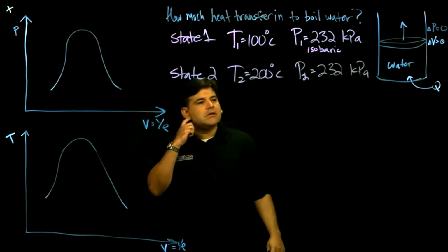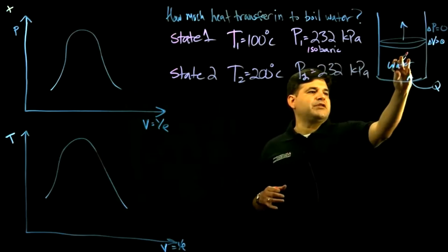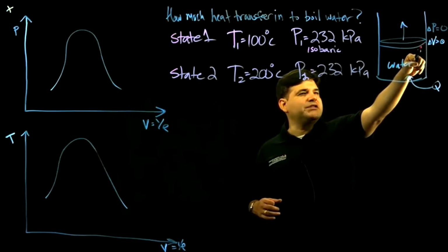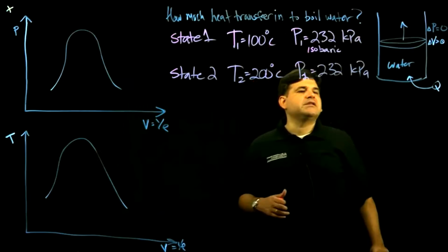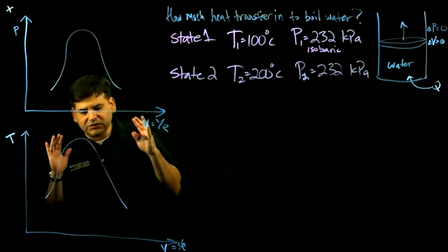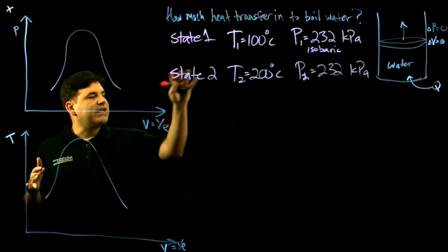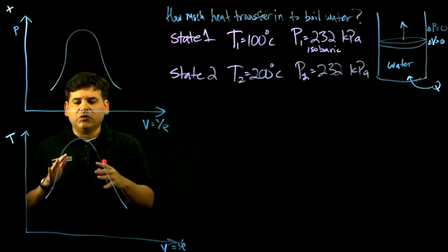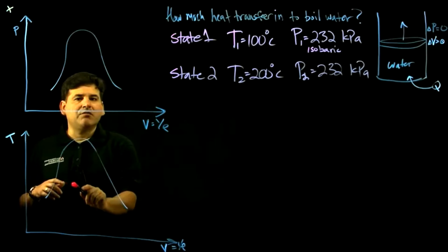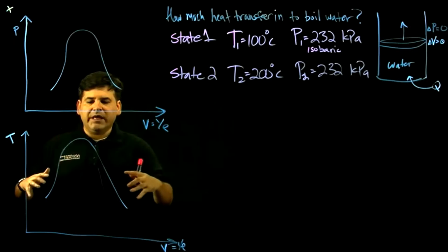All right. So we're going to analyze this going from an initial temperature, this heat transfer comes in to keep the pressure constant, this volume changes, and the final temperature is 100 degrees hotter. So we know that this is water, and when we don't know the state of the water that we're working with, the first question to ask is whether we are on this boundary or somewhere inside the middle, because we don't know where we are. We can be compressed liquid, we can be superheated vapor, or we can be anywhere in between.